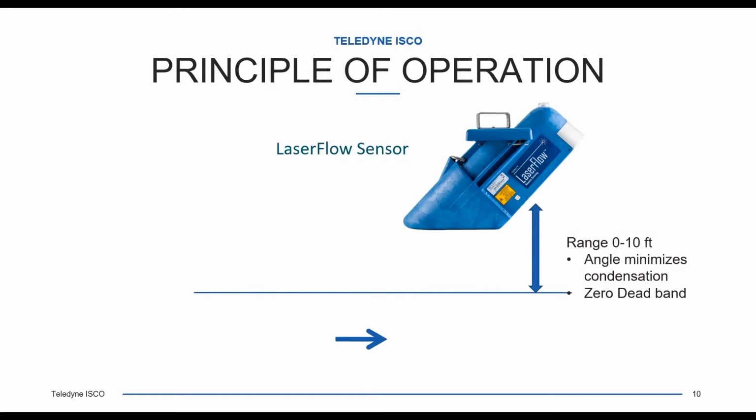You'll also notice it's angled. The reason we did that was so that any moisture that's in that manhole that collects on that sensor face will just run off the sensor. You won't have to go in and do any kind of maintenance, typically, with the ultrasonic sensor. Whether it is submerged and becomes unsubmerged, you should not have to clean that. Okay, so now we get our level measurement, or we know the distance. Now we measure where the water is.